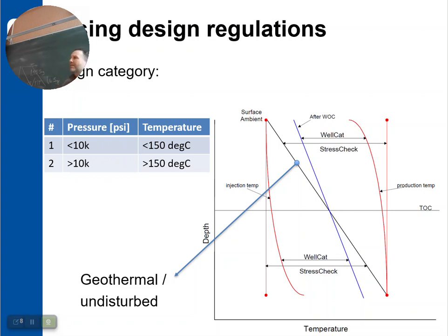There are more differences than that between Velcat and Stress Check. Velcat models wellhead growth, the thermal expansion of the steel coming up, the wells trying to come up. It models packer forces on tubings. It models several other things too. And you can set up very, very special cases, like a plug in a well and see what happens with the leak above and below, and so many special custom loads. That's kind of cool.